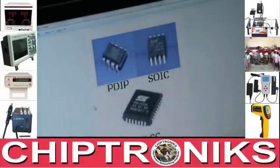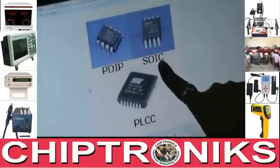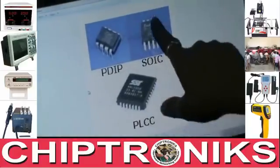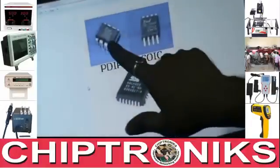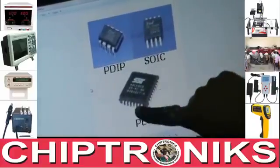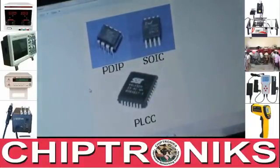BIOS. This is the PDIP IC. It is used on desktop motherboards, and SOIC is also used in laptop motherboards and desktop motherboards. PLCC has 32 legs, SOIC has 8 legs, and PDIP also has 8 legs. This is a DIP socket IC. This is SOIC. And this PLCC IC, we call socket IC. We fix the SOIC on the board directly, and this one we fix on a socket.